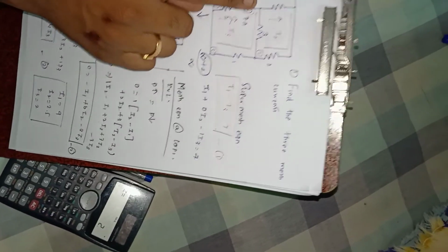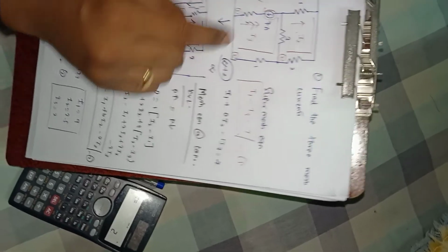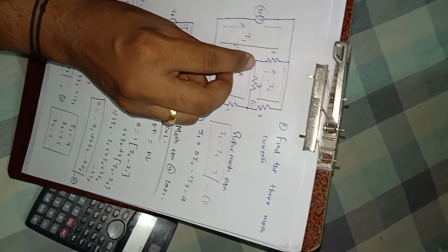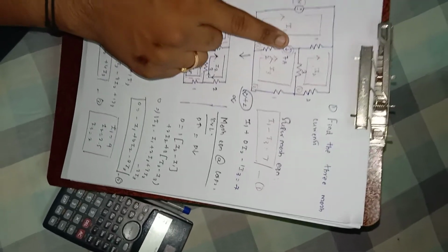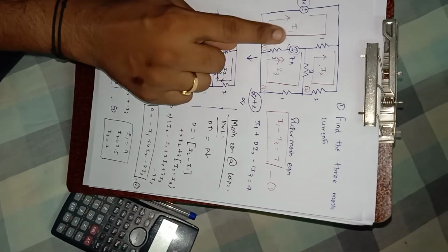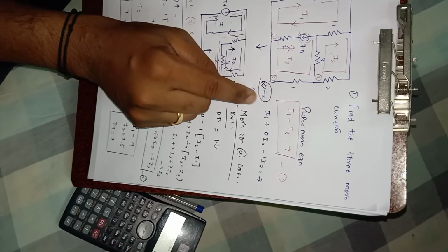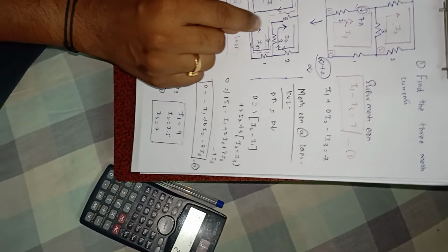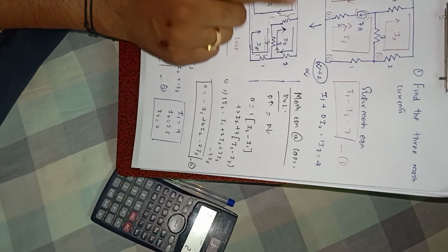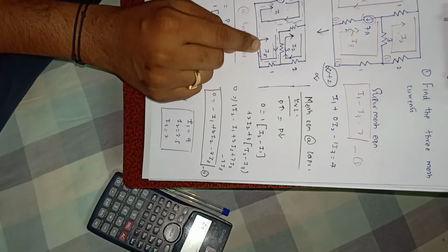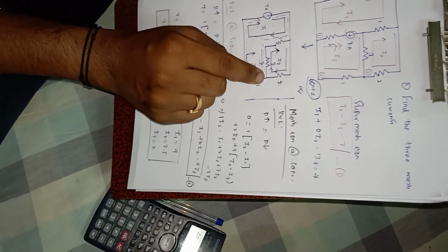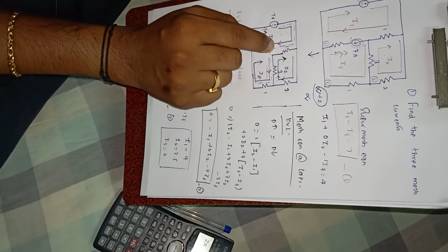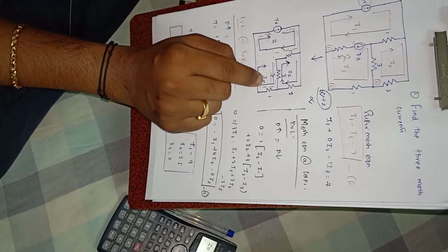Now we have to lift off this 7 amps. When we lift it off, this is an open; the equivalent for the current source is an open circuit. The open circuit will have infinite resistance. Infinite resistance plus 2 is again infinite, so no current will flow through this, so we can simply wipe off the complete limb, and then your I1, I2 and I3 completely exist. But your I1 current has the major direction, so you give the direction of your I1 in the third loop also.